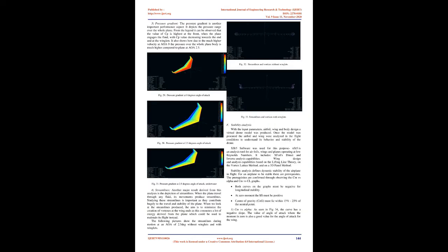4. CL/CD vs alpha. The lift-to-drag ratio versus alpha explains the flight economy, i.e. the amount of drag incurred to lift gained. A higher lift-to-drag ratio corresponds to higher lift for the corresponding drag, which is suitable in our case. From the graph in Fig. 13, it can be seen that as the AOA increases, the L/D ratio increases, but it eventually reaches a critical point before falling. Comparing multiple graphs, a suitable AOA can be chosen.